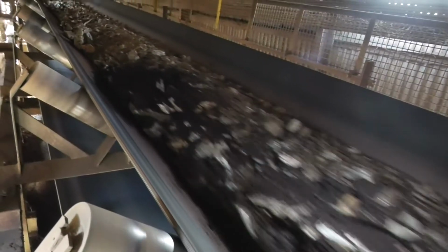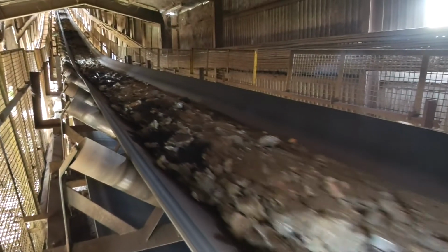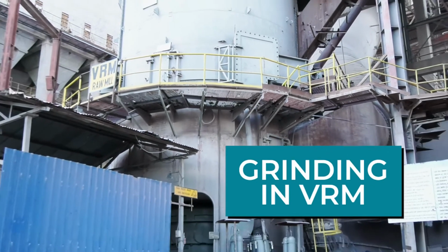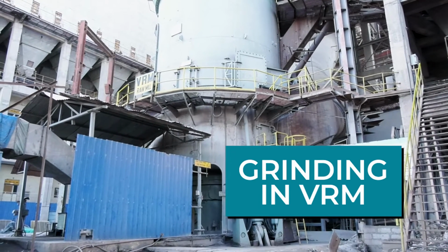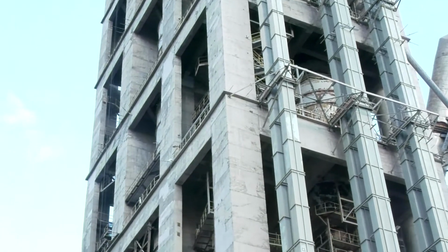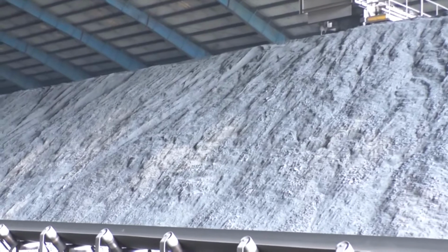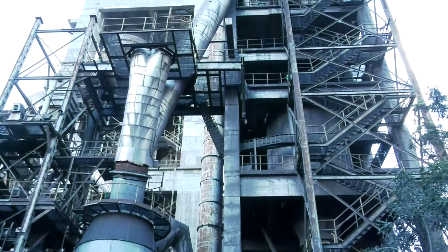Raw material is extracted from the hoppers with controlled flow and conveyed to the vertical roller mill. Grinding in VRM. The vertical roller mill grinds the material to optimum fineness and the ground material is transported to the 6-stage preheater by elevator. The pet coke or coal grinding is done with another vertical roller mill for pyroprocessing.